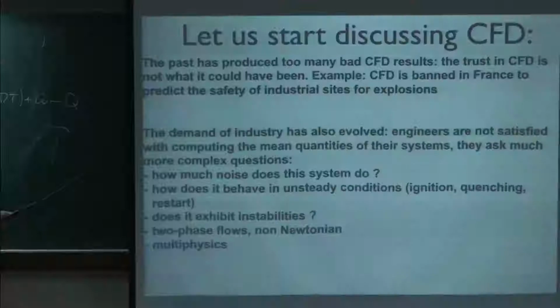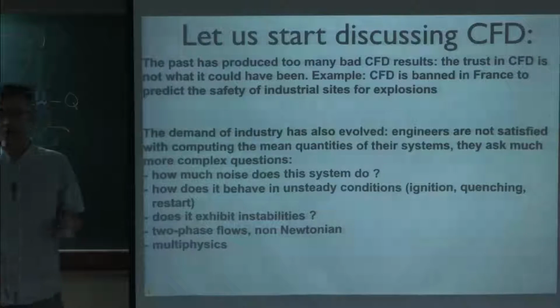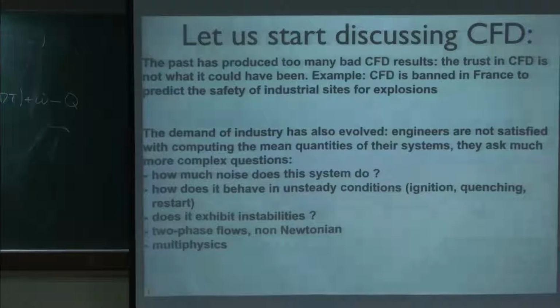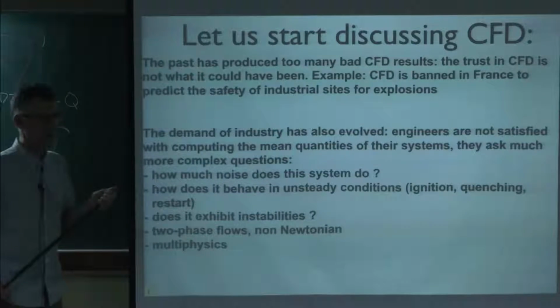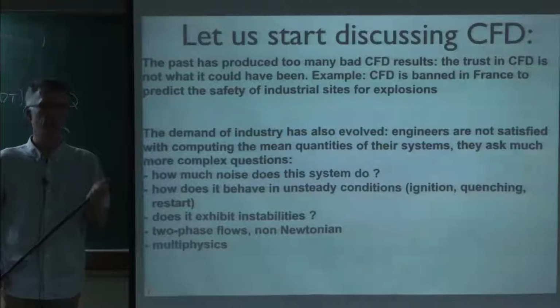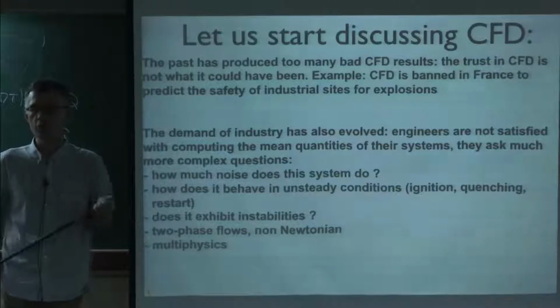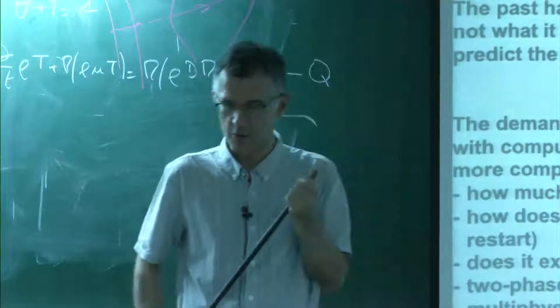But why is it so? Well, because so many people have done so many bad computations that they feel it's no use. And it's a dangerous trend also in industry. You go to industry, you sell CFD, you come back 5 years later, the results are not good, they say, okay, it's not working, out. So it's really a problem today to recognize that we need to do good CFD, not only CFD. So Stanford has this famous sentence saying, not all LES are equal. The fact that you do an LES doesn't mean it's a good one. You need to do a good one, and that's much more difficult.